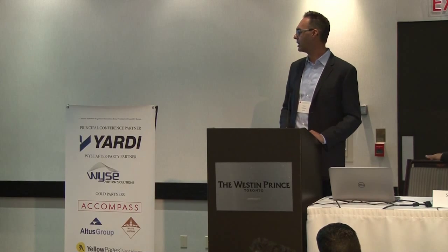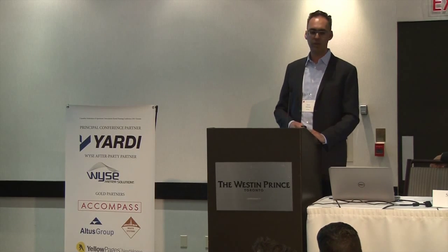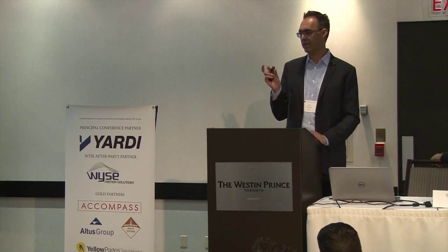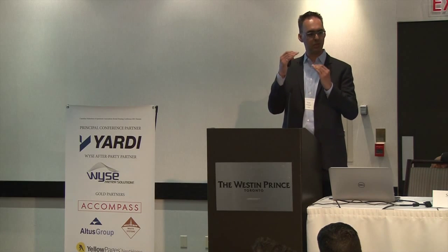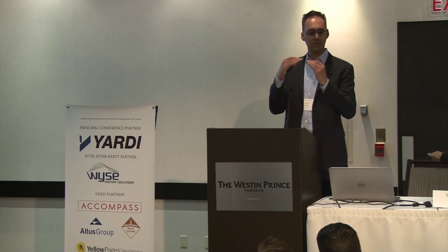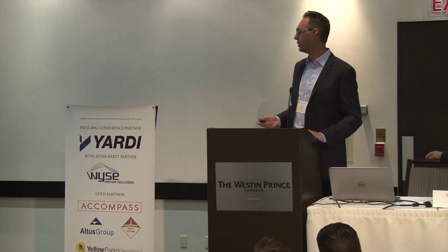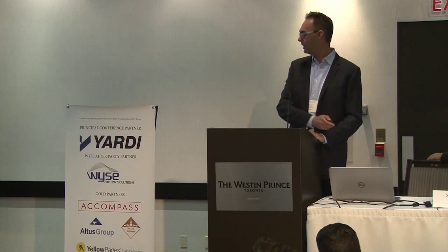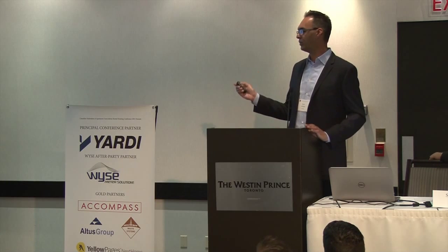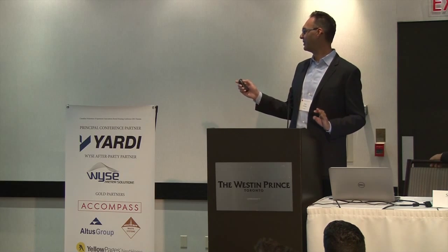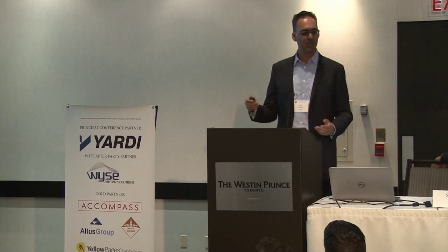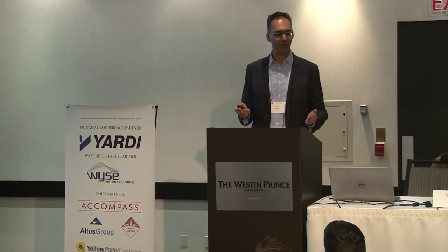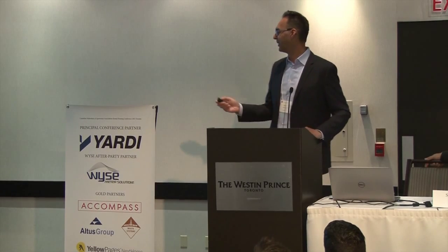Today, in more modern construction, the lateral connection is provided with a little piece of metal, which is flexible, so it can absorb some vertical movement, and it still provides that lateral securement, which is critical. So, I'm not trying to show you these extreme examples, but it just gets the point across. I hope I'm not coming across as showing all the bad stuff.